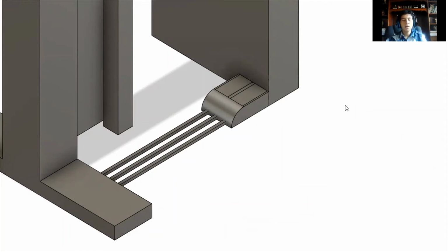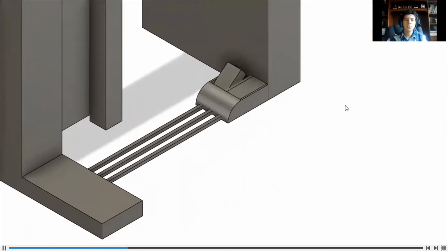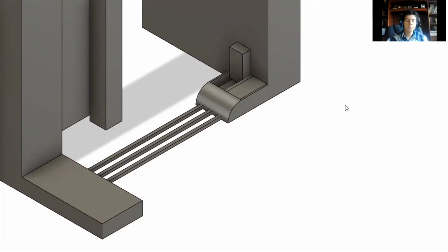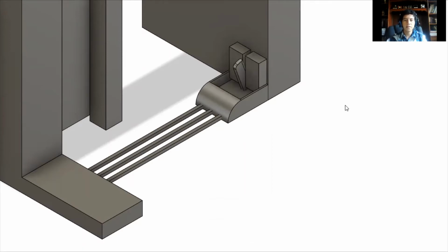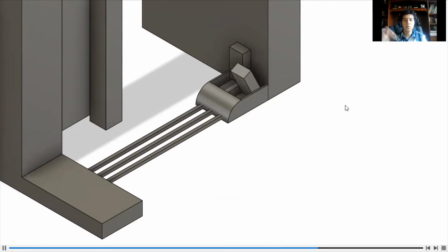So when the machine starts to reach the last lap, the first actuator is going to move to put itself between the paper and the final lap of paper. Then when the machine reaches the final lap, the second actuator is going to press the paper and finally cut it. After that, the three actuators are going to restart to the original position.